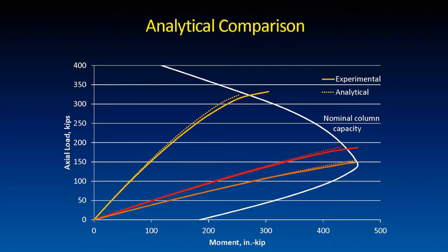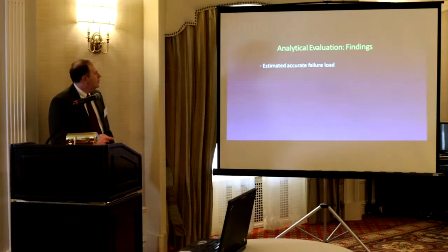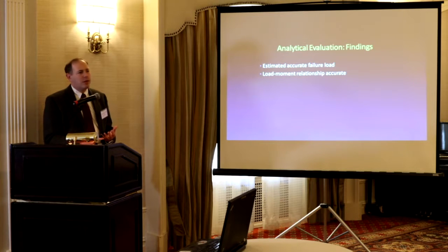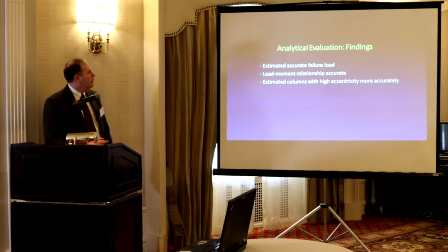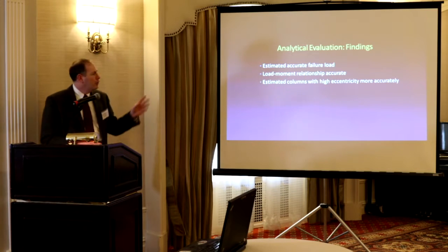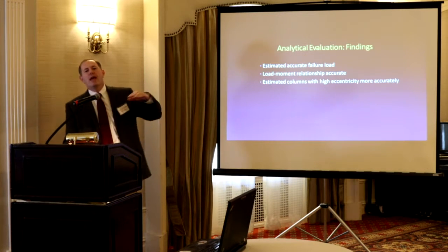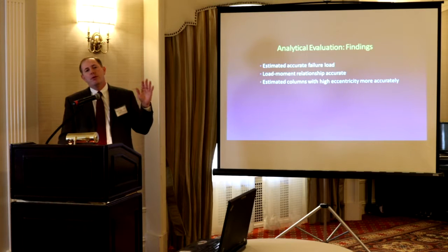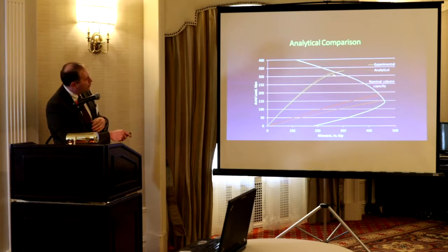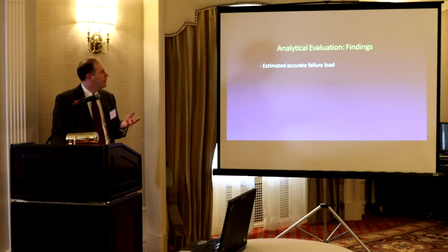This is short-term effects. So we estimated the failure load accurately. The load-moment relationship works out. We did estimate with high eccentricity, so there's quite a bit of bending on those columns, a little more accurately than when we had very high load with very little moment. We were maybe a little more divergent, and you can see that actually back here, a little divergent here. These were almost hitting right on top of the curve.